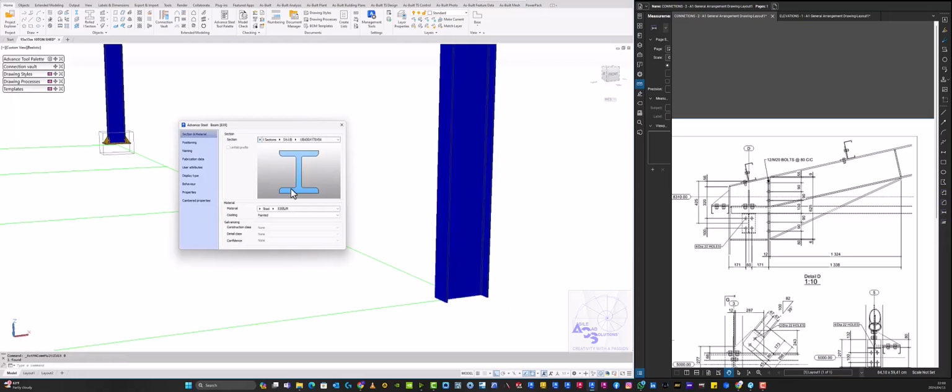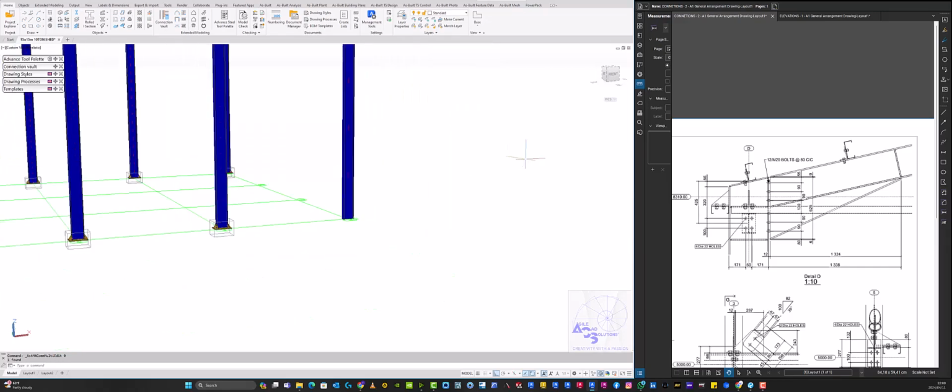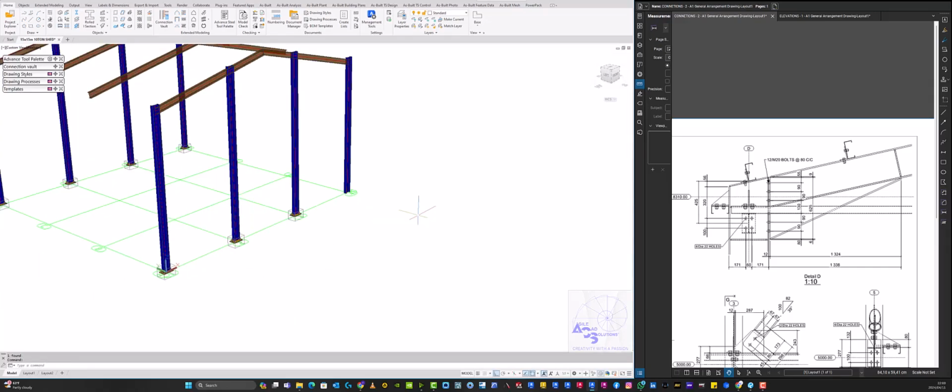So let's just change back the display. Display type, then we go to standard. All right, then after that, we just have to select and copy. If you know the distance between the grids, you don't need to pick an exact point. You just pick a point anyway. Add your 5 meters, enter, add the second column, which is 10 meters, then enter.